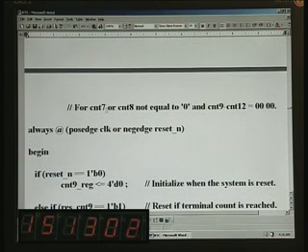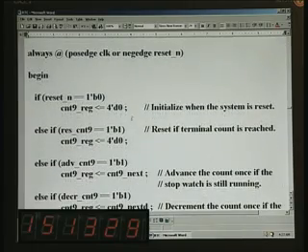And this is the condition for presetting counter 9: the 7 or 8 counter must not be equal to 0, and counters 9 through 12 must be zeros. So this is clear. If all of them are 0, it has come to the terminal value, so there is no further decrementing. Only to take care of that we are putting here that at least one of them must be not 0. And as usual, counter 9 implementation is here: the reset condition, then advance, then decrement condition.